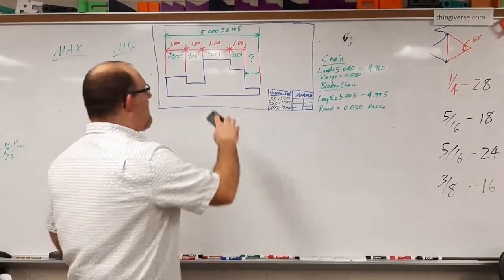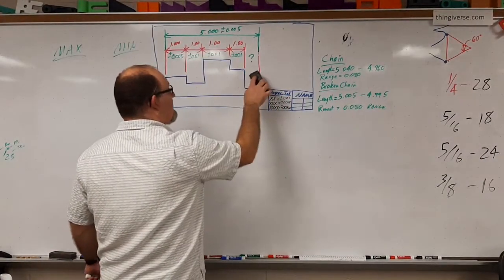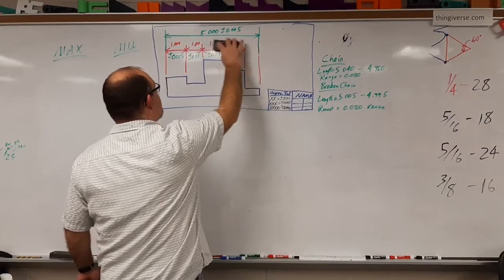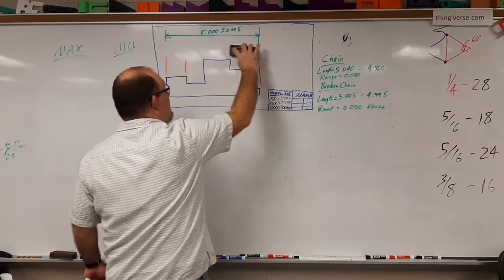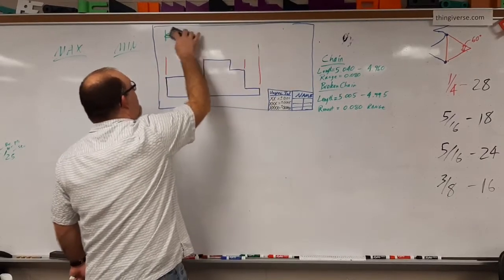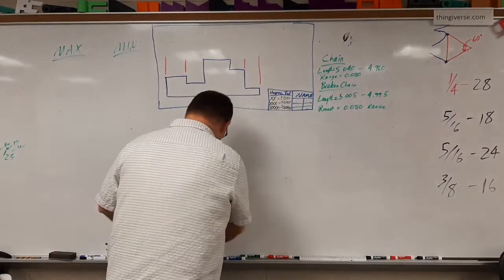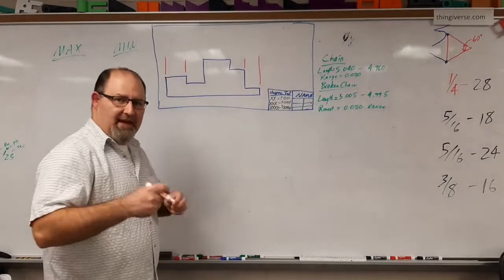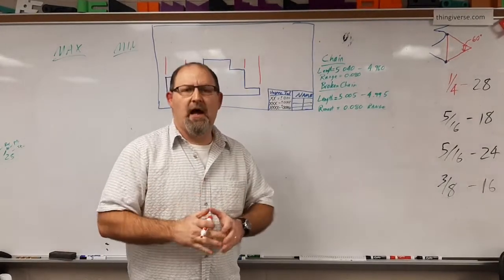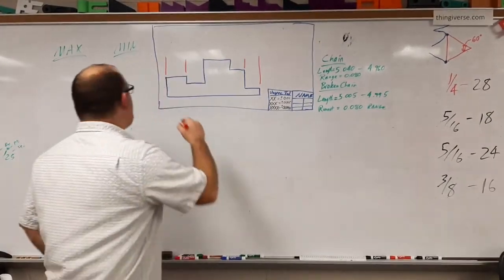This next dimension, called datum dimensioning, is a little bit different than each of these, in that all of these now are going to go away and not be dependent on each other. Datum dimensioning establishes what's called a datum point or a locational edge.